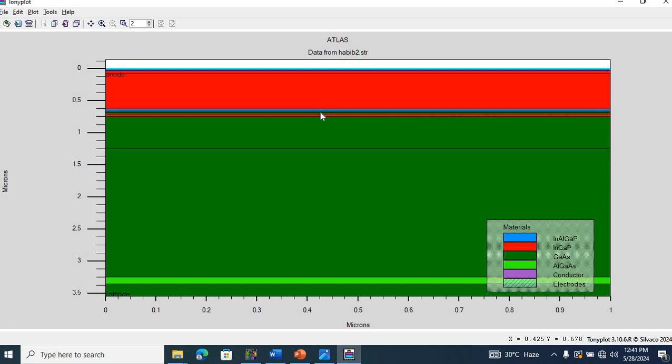Third, it provides voltage matching, which is a critical aspect of a multi-junction solar cell. Each semiconductor layer in a multi-junction solar cell should operate at its optimal voltage for maximum efficiency. And the tunnel junction helps to achieve voltage matching by allowing the voltage across each junction to be independently controlled. And this ensures that the voltage generated by each layer adds up constructively, leading to higher overall efficiency of the solar cell.